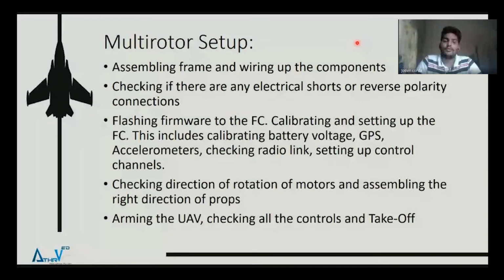Then you can set different modes, like if you want sport mode, or level mode, or acrobatic mode. So setting up those channels is next, because unless and until you set up channels, the quadcopter will not get to know what you want the UAV to do.